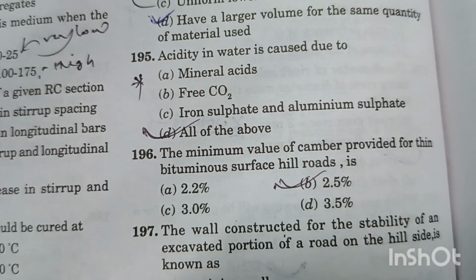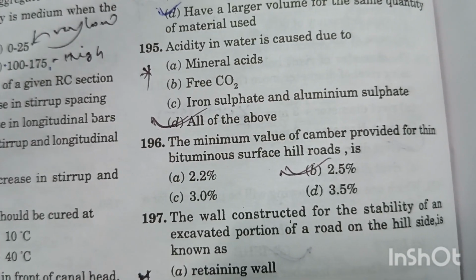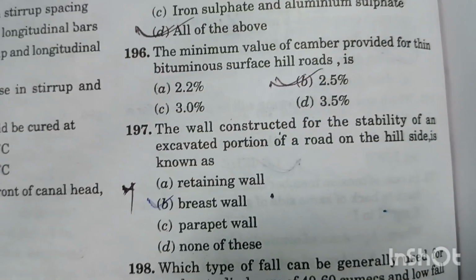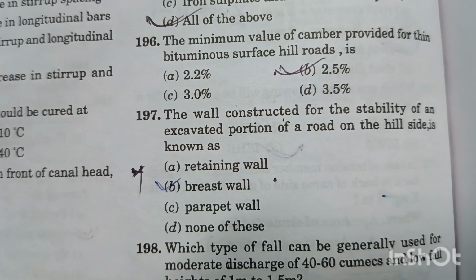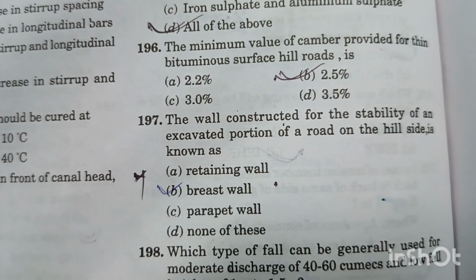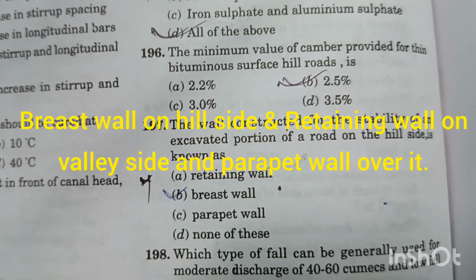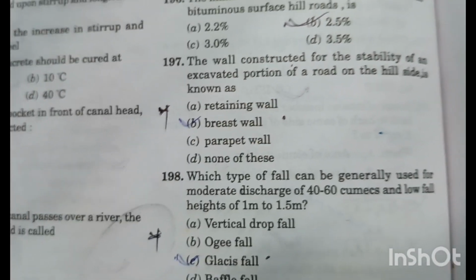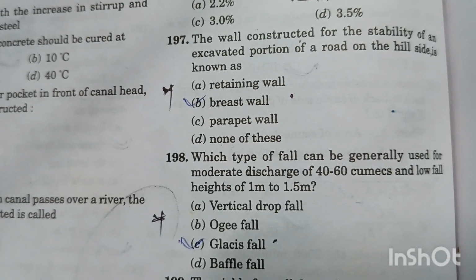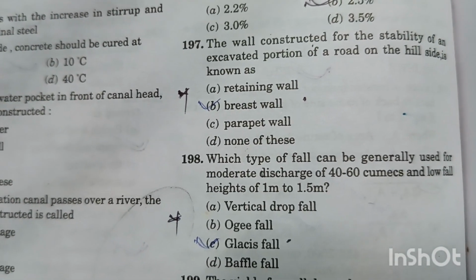Question number 196. Minimum value of camber provided for bituminous surface hill road is 2.5%. Option B is the right answer. Question number 197. The wall constructed for the stability of an excavated portion of a road on the hillside is known as breastwall. Option B is the right answer. Question number 198. Which type of fall can be generally used for moderate discharge of 40 to 60 cumecs and low fall heights of 1 meter to 1.5 meter? That is glacis fall. Option C is the right answer.